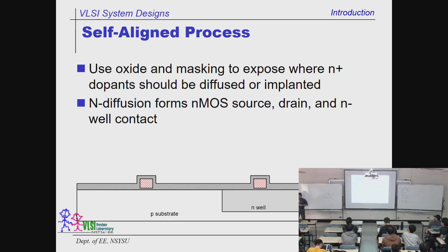And then we go through the similar steps again repeatedly. And this kind of process is called a self-aligned process. This is where the difficult part is. TSMC right now is the best in the world. They can do the alignment really well. And this is why Samsung or Intel or those companies in China right now cannot catch up with TSMC, because when it comes to very, very thin, advanced processes like 1 nanometer, 3 nanometers, it's up to how well you control the machine.